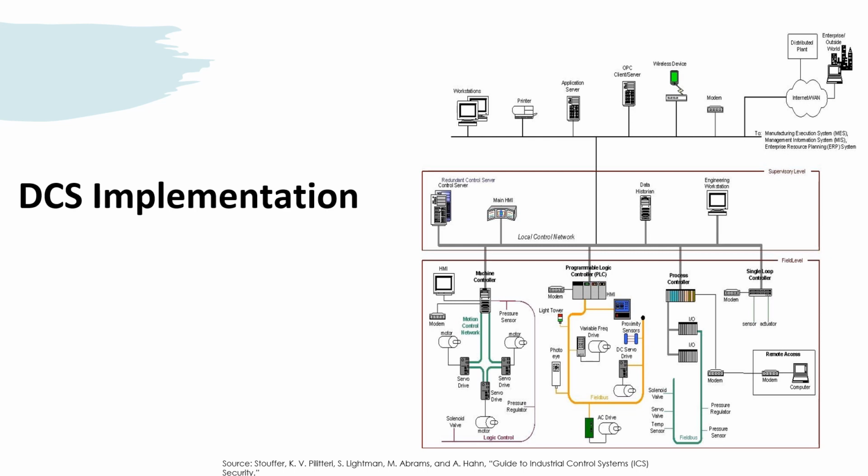The multi-level DCS includes components from the field level all the way up to the enterprise level. Similar to the SCADA system, a major subsystem at the supervisory level includes, among other things, the control server, the HMI, and historian that facilitates management, monitoring, data gathering, and control capability for the system. The control server communicates data set points to and from the distributed field controllers, which control their process actuators based on control server commands and sensor feedback from process sensors.